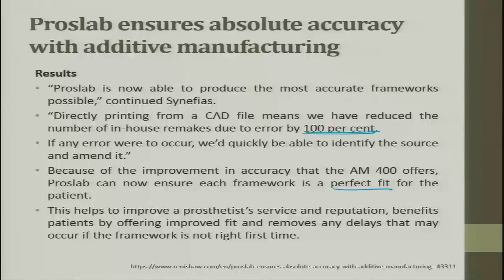And again here, by using all these RM techniques, additive manufacturing or rapid manufacturing techniques, the example I present in this case study is a single part product. If you want multiple parts getting assembled into a product, even now it is a challenge. So the way out, when we talk about rapid manufacturing, is to make the product or part structure more complex and reduce the number of parts, so that what you make is perfect and the delivery is on time.